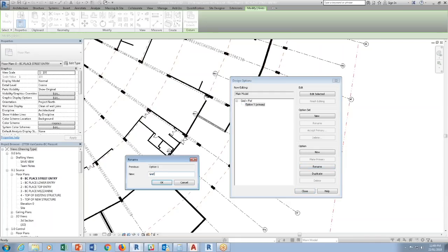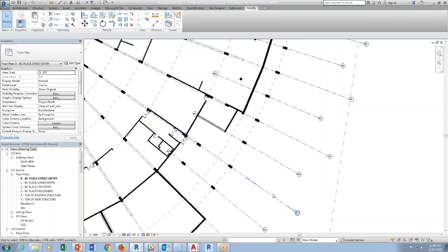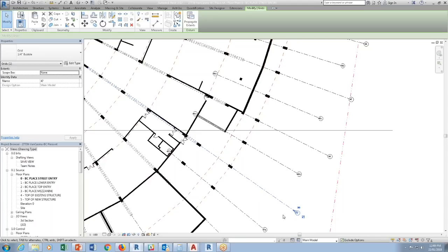In here, I'm just going to rename, same thing, just grid plus ref. Okay? Simon, can you explain how this is different than having it in Pin? Our work sets? Oh, okay. Work sets won't do anything. You can pin. People can unpin it. Okay? Pinning doesn't work. Work set, it just basically hides stuff. It doesn't do much. Okay?